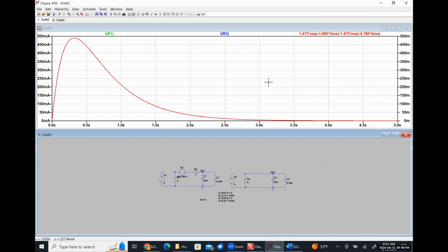Yes, David, how may I help you? The initial conditions are just the circuit at t equals zero minus. I do that just because I'm too lazy to remember how to make a switch work. It's easier for me to just say it had this value than setting up a switch to actuate at the right time and all that kind of jazz. So yeah, the initial conditions, 100% correct, are just what's going on in the capacitor and the inductor at 0 minus.